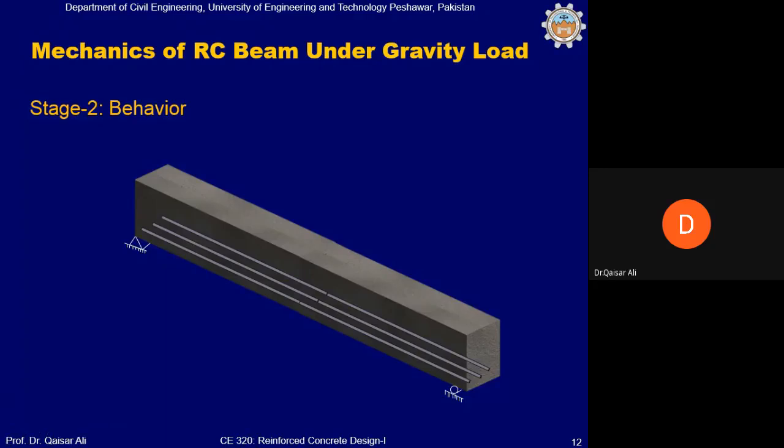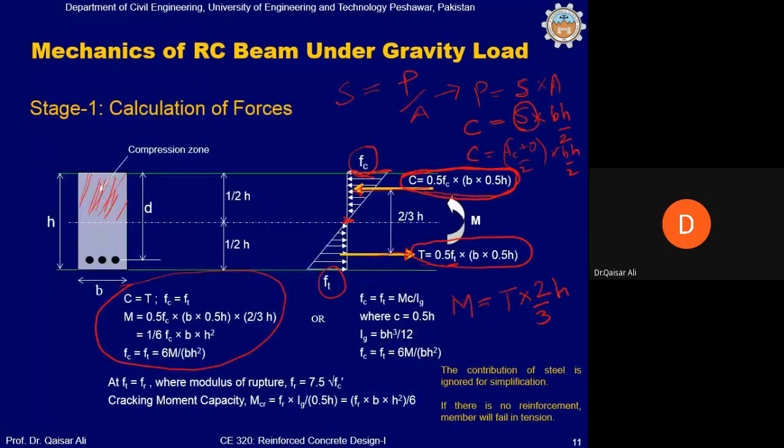So when this internal bending moment, which we will now call the resisting bending moment, MR, is internally resisting the demand bending moment M produced by P, and this MR is greater than the demand bending moment, then the beam will not collapse.